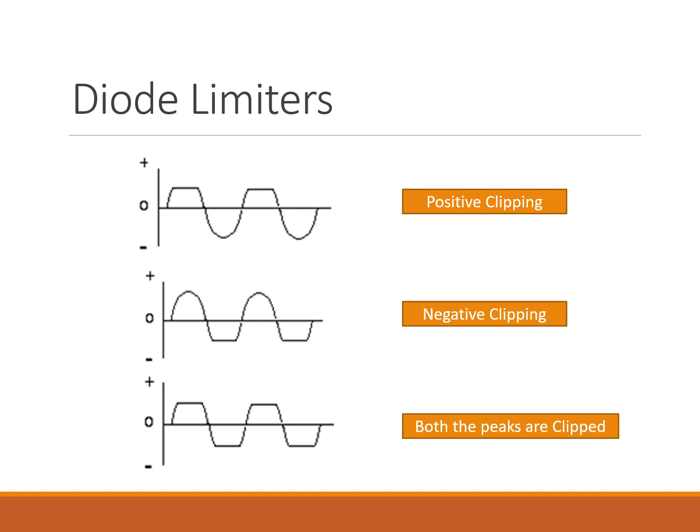So we introduced the idea of diode limiters or clippers. Now it's time to visualize the result. Let's look at these three basic clipping configurations and what they do to your waveform. First, positive clipping. A diode is placed to conduct only when the voltage exceeds a certain positive threshold, so that portion of the signal is chopped off, or clipped. The output looks like only the negative and lower half of the signal passes through. All the positive peaks are flattened. A good use case is to protect input pins on microcontrollers from high voltage spikes.